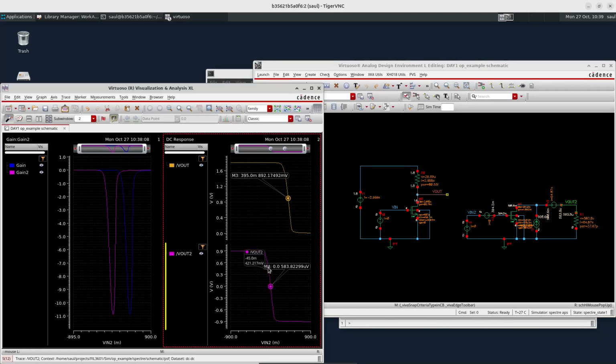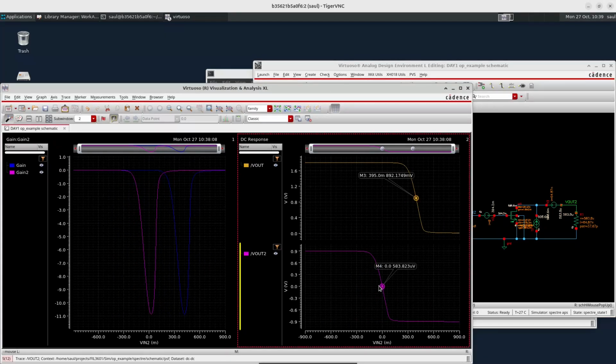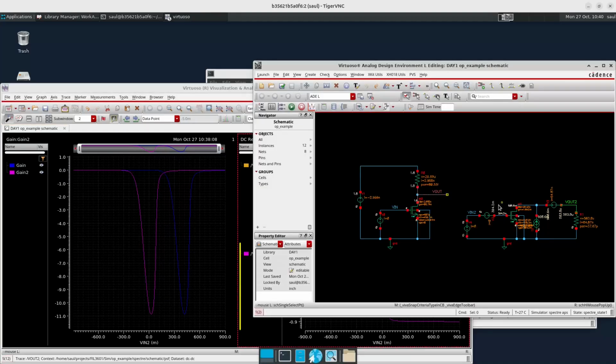So we have effectively removed the operating point. This one has been centered at the origin, and it is very nice because I don't have the problem of the operating point being shifted to a particular voltage. So I have moved the operating point to the origin just by adding the gate to source voltage here, the drain to source voltage here, and the current that is entering the transistor here. So we will find practical ways to find these voltages and currents very soon.